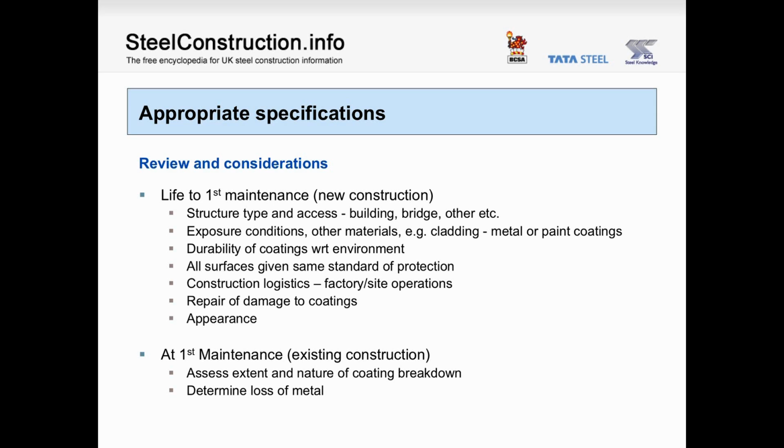Also, the protection of other steel surfaces, including fasteners and decking, etc., should be considered at the same time as for the principal structural members. Such components may require additional coating to achieve this. It should also be recognised that some of the surface treatments may be part factory and part site applied. Site stored coated steelwork may well need to be cleaned before finish coats are applied to avoid adhesion problems. Should coated surfaces be damaged, a method of repair should be stated to avoid a localised premature failure.